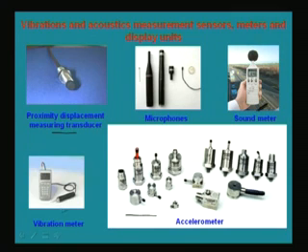There is also a pocket vibration meter, I should say. This gives displacement, velocity, and acceleration components, maybe RMS or peak-to-peak values of that. And these are the microphones; you can see that a variety of microphones are there, and this tiny one has a very high frequency response, even the sonic boom, those frequencies they can capture very accurately. So these are the various vibration and sound measuring sensors.